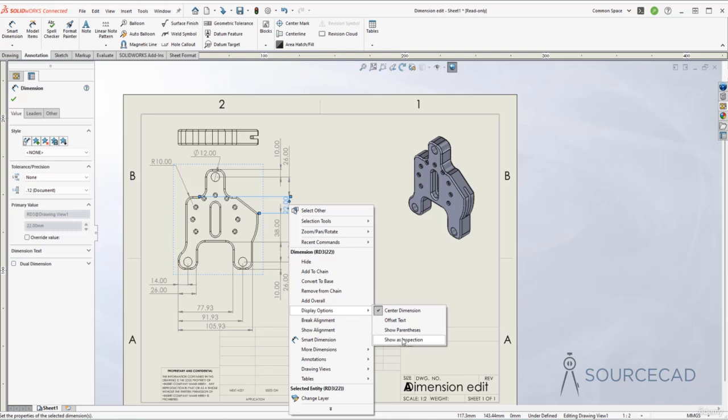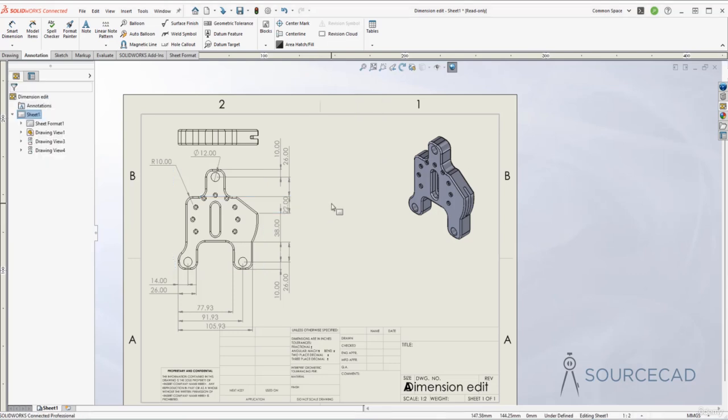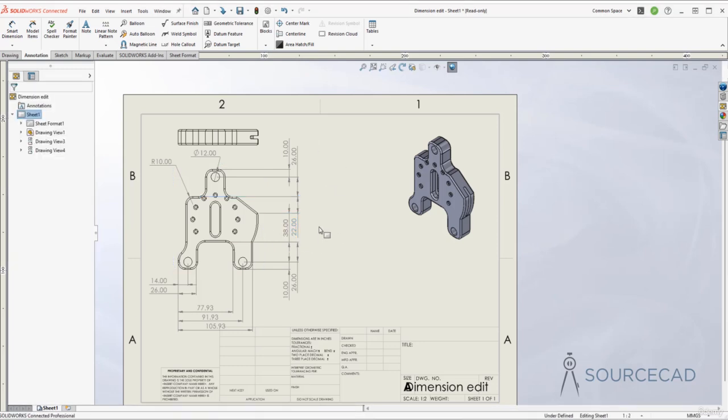And as you're familiar, these options are also available in this flyout. So we have the parenthesis here and the inspection here, and also this is centered. So all these options are already available in this flyout. So that's how you can add the dimensions. Now, after adding these dimensions, I just noticed that this 22 unit was kind of cramped in a small space. So I'll just move it out just to make it look clean. And that's how you can modify the dimension settings.